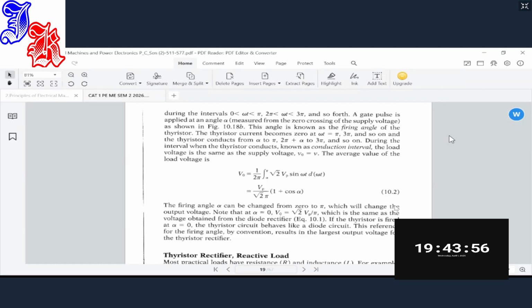Yeah, it's still the same as the first one. Thank you, Peter Chege. It's still 108. The moment you ignite the thyristor at 0, it will give you the same result as that of a diode. So maybe we'll check where you made a mistake. Then let us ignite it at 60. Let alpha be 60 and ignite the thyristor.